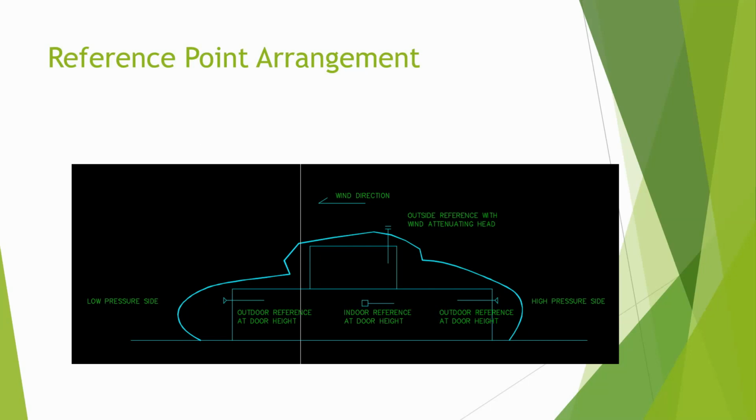And so the wind has no effect on that sensing point in that case. Now I drew the picture of it above the stagnation range. Exactly where that is on a building is kind of difficult to determine. Certainly you'd like to have the thing as high as possible. You want to mount it to the highest thing possible.